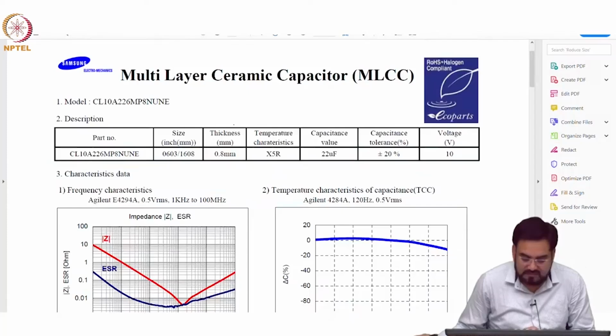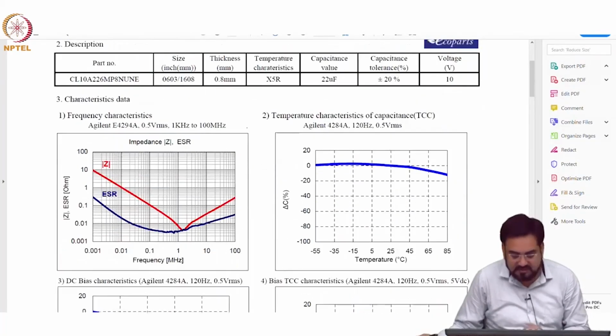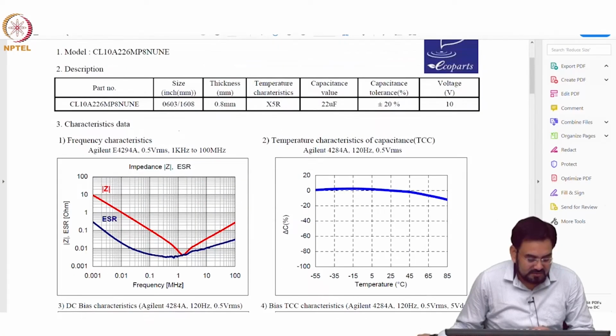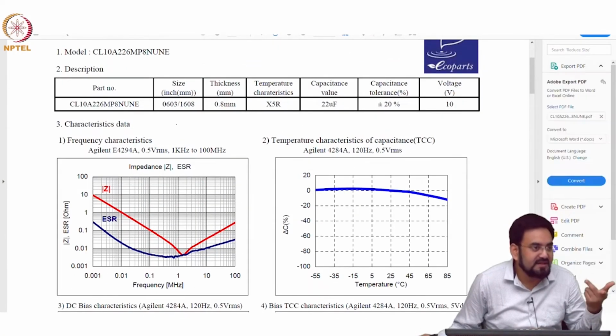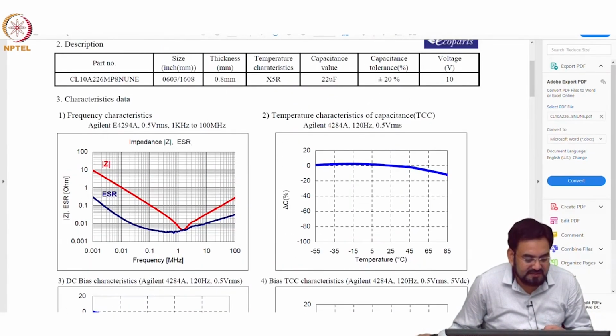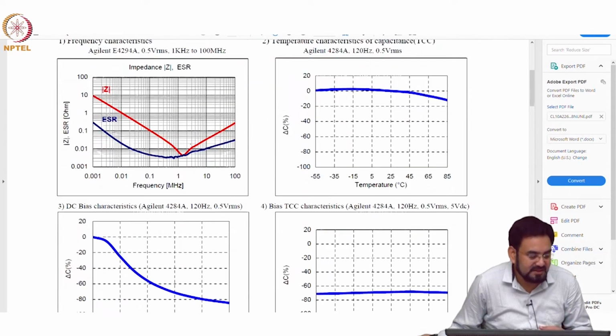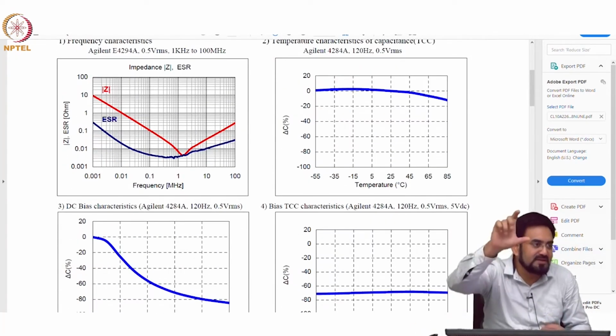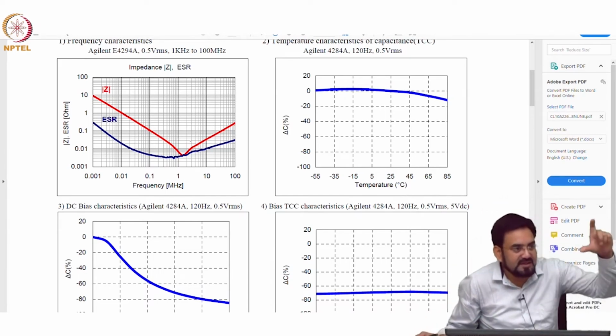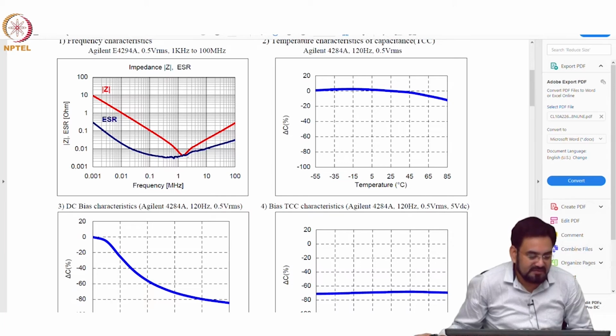So, let us see. Okay, first let us look at the capacitor. If you remember, I mentioned the voltage derating and resonance. Resonance will happen if a capacitor has inductance. Just like the equivalent series resistance ESR, you have an ESL, equivalent series inductance. You can think of it as a series LCR: the capacitor, then series R and series L. It will have some resonance, and at that resonance your impedance will be the same as your resistance. So, this is your ESR, this bottom point.